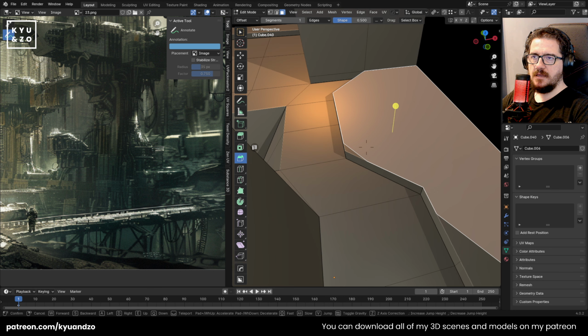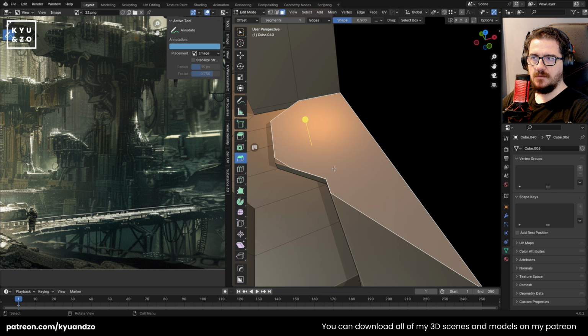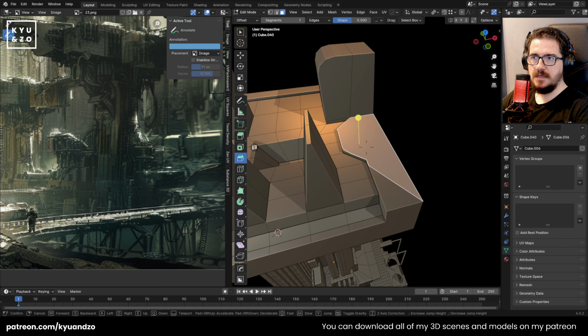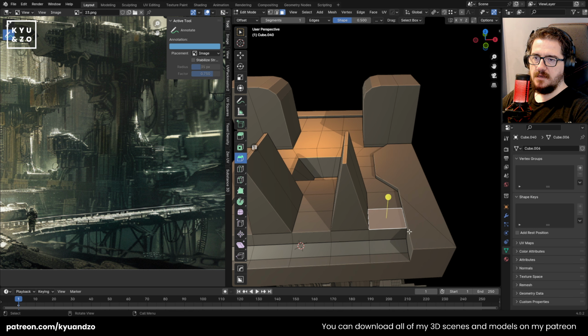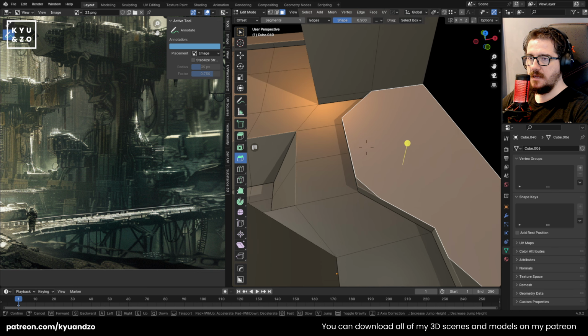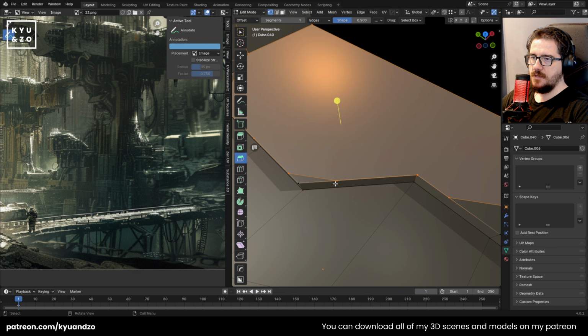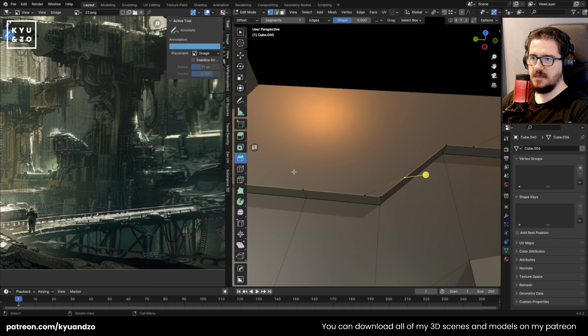And yeah, as I said before, I showed you the trick. So let's say you want to use this area, okay? Maybe you want to extrude it, you want to use it in any case, but as you can see, it's a problem. How can you solve it? I showed it to you on previous episodes, so it's so easy. The first thing, just clean up these unwanted vertices, okay?